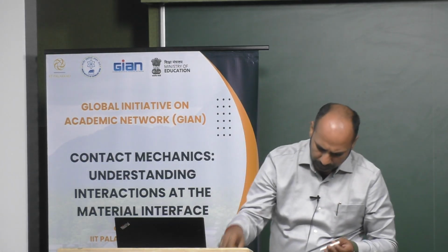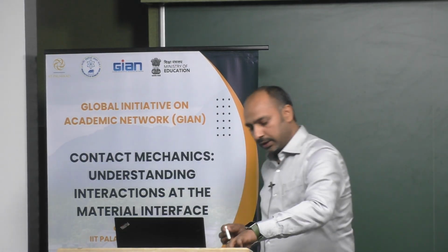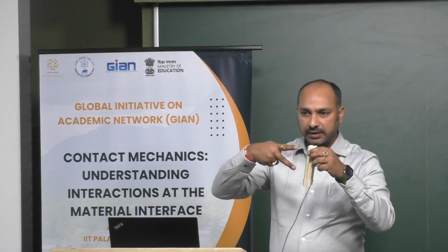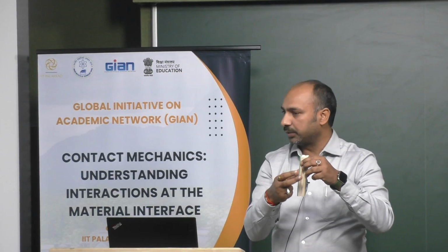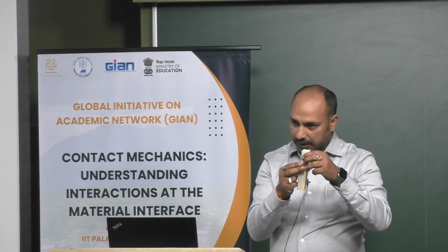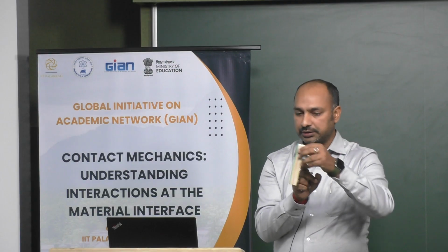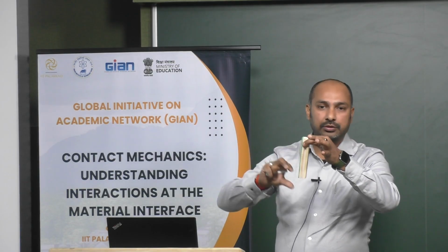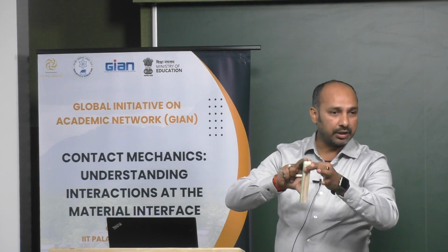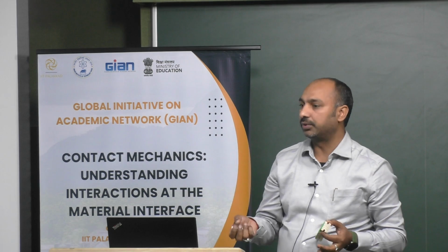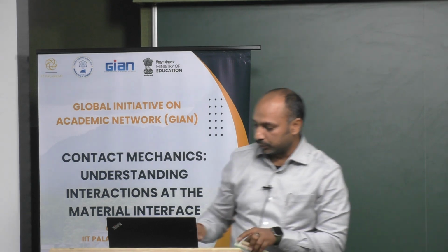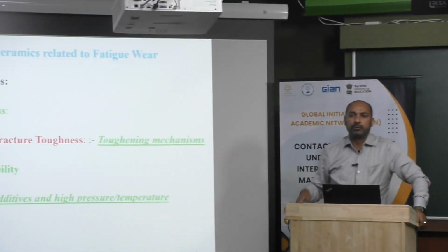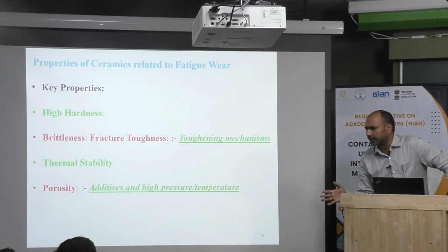So this surface gets fractured, but the other surface will not get fractured by this energy. The energy is transferred at the atomic level to this side, and again that surface gets fractured, but some energy is absorbed by these atoms, or the particulate or fiber element. This is how you can improve the toughness of ceramic, and that is considered the toughening mechanism.